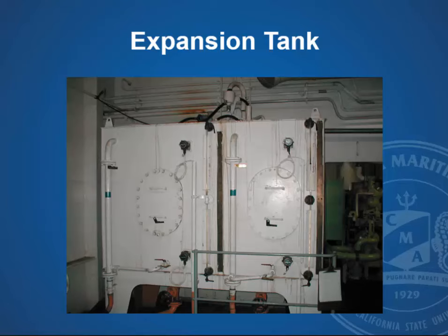If you are leaking, you first do an external exam of all your pumps and valves and fittings. External leaks, if they're minor, are really not that large a problem, but of course as part of a normal maintenance procedure you're going to take care of them as soon as possible. But if you can't find any external leaks, then you have internal leaks. And internal leaks, where you have cooling water leaking inside the engine, can be really detrimental for corrosion and other problems that it will create.